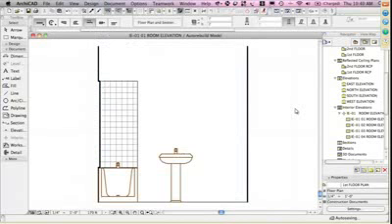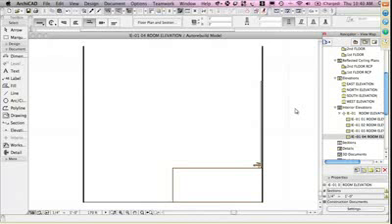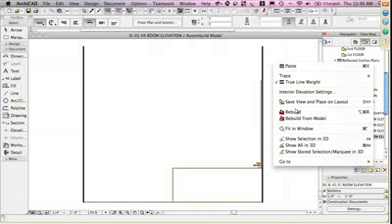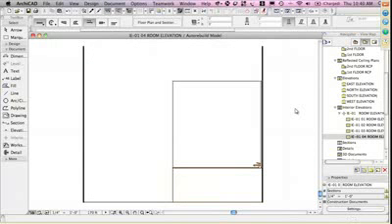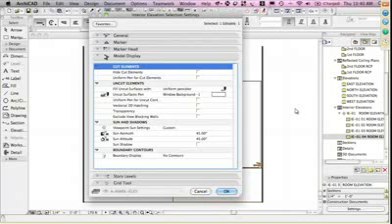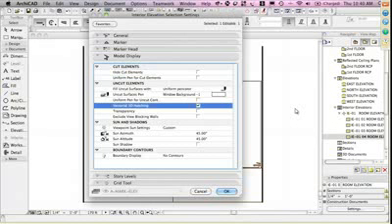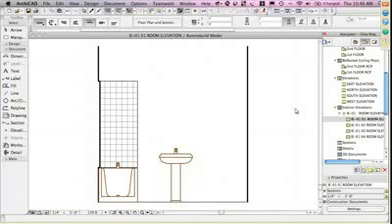When I say OK, we'll see there is that view, and let's see, we're in IE01, so probably number 2 here would be, no, let's see, maybe it's number 4 then. Oh, and we have to do the same thing in each one of these elevations, or select the whole group and turn off exclude view blocking walls, and say OK. And then we also need to go to the interior elevation settings and say we'd like to show vectorial 3D hatching. So we need to show the hatching and exclude the view blocking walls. And now we're seeing both of these interior elevations beautifully, just the way they should be.